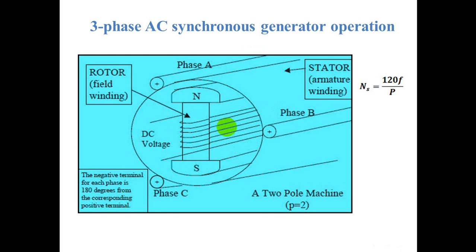The direction of induced current can be determined using Fleming's right-hand rule. Thus, we can say that current will pass from A into B, the current goes from A into B, and from C into D.